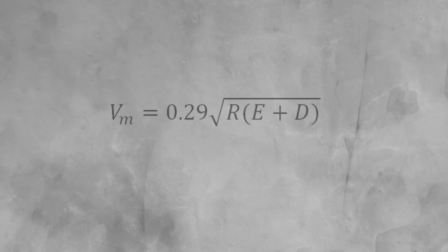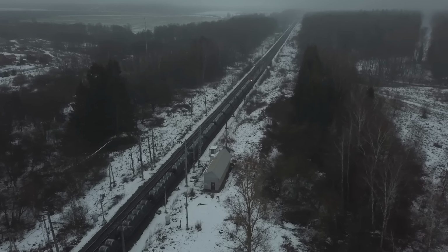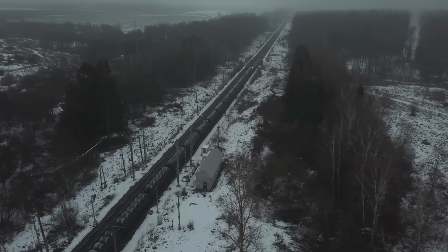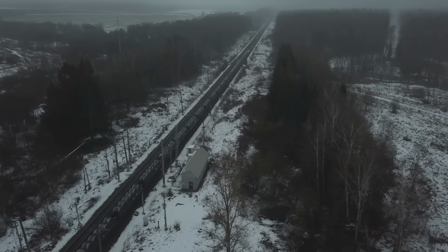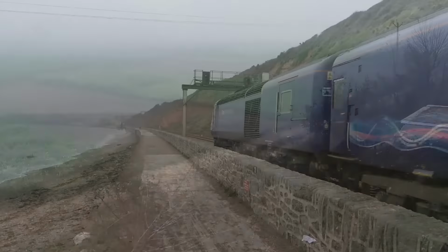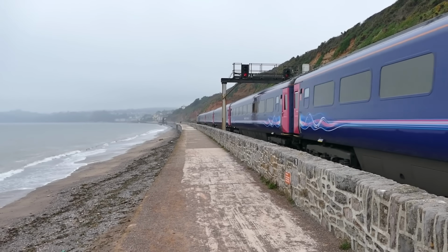For example, we can find out the maximum speed a train can travel on a curve, if we know the radius and cant values. Getting the design of a curve wrong can have major consequences. At the top end is trains overturning and derailing, leading to potential loss of life. At the other end of the spectrum, it can lead to an uncomfortable ride for passengers. While this could be overlooked, fare-paying passengers are the end user of the railways, and their experience does matter.